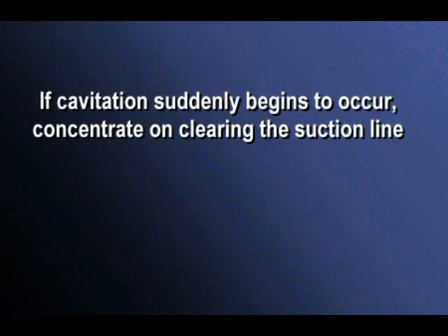If a pump has been operating normally and then becomes noisy due to cavitation, suspect suction blockage. There might be grease buildup, debris blocking the line, or a suction valve may be partially closed.